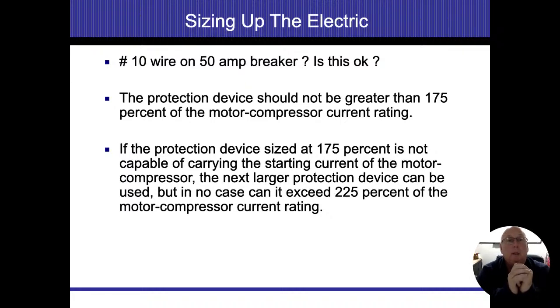So the shortcut, if we remember, we had our amperage written first, and then we had our copper conductors and our aluminum conductors. So 15 amps was a 14 gauge, 20 amps was a 12 gauge, 30 amps was a 10 gauge, and 50 amps went all the way up to an 8 gauge. So the rule of thumb for us is whatever wire we have there, and that's only specific to those dedicated circuits, all right? Once I start mixing circuits, I can't do this any longer. It's only when it's dedicated.